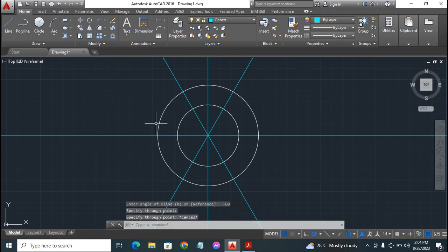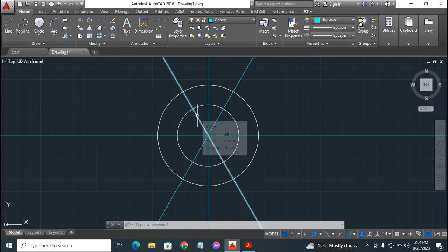Next up, now from our PDF document, we'll find out that the width of those protrusions is 8 millimeters in size. So all we need to do is to start offsetting. This construction line you see is right at the middle of those protrusions. So we are going to offset on both sides of this construction line at a distance of 4 millimeters each, altogether making the 8 millimeters width of those protrusions. Okay, so quickly let's do that.